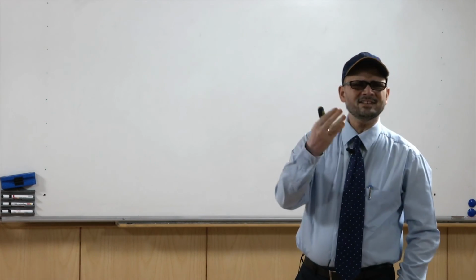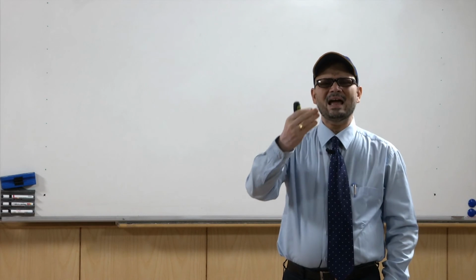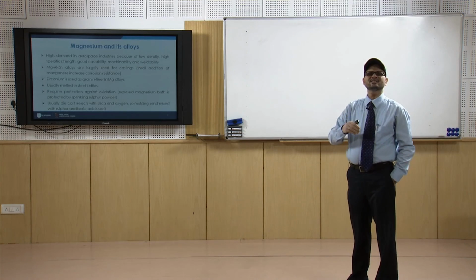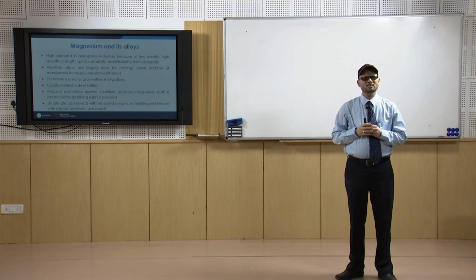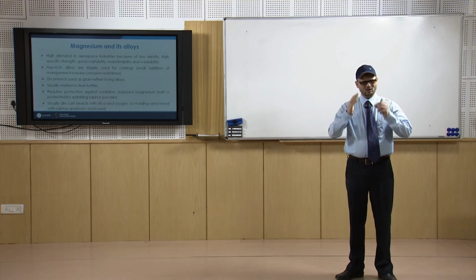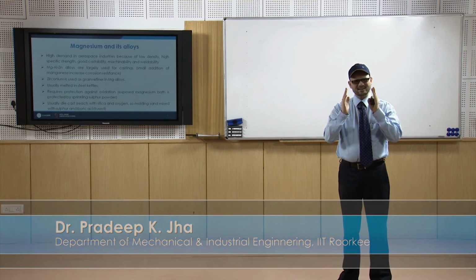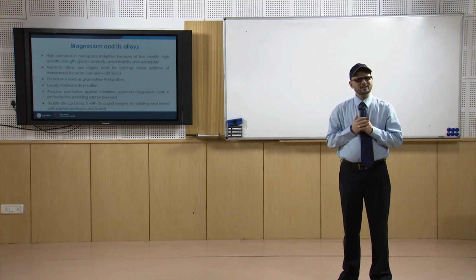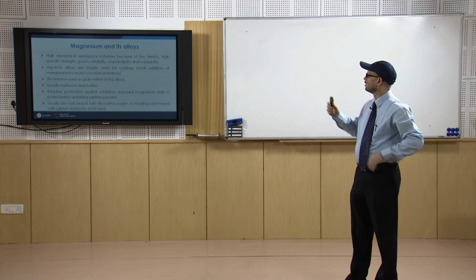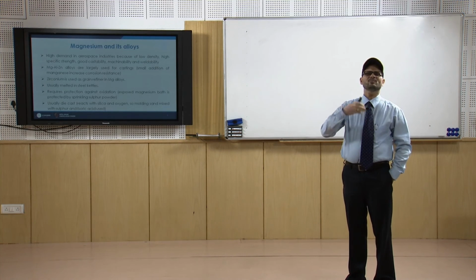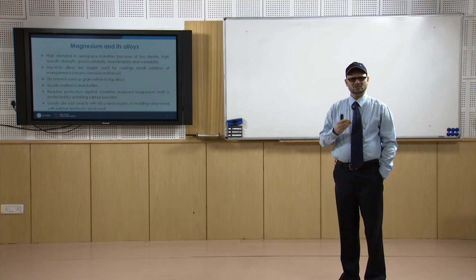Then you have titanium melting. Titanium is a very reactive material. So, for titanium melting you will have again a controlled atmosphere to melt the titanium. So, you can see that most of these non-ferrous materials are preferred in many senses because of their low melting points, but they have to be melted under a controlled atmosphere normally, so that there is minimum chance of the formation of the drosses or non-metallic inclusions, and then you can get a suitable cast quality.